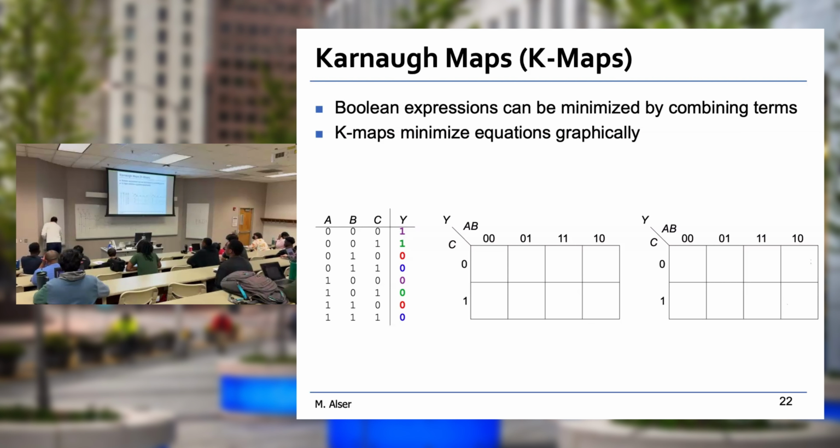Now, we need to build a new table. And this is what we call a Karnaugh map, okay? Now, since we have 3 variables, we always split them into 2 and 1. 2 variables and 1, okay? All the time. Since they are 2 and 1, how large should this table be? For 2 variables, how many permutations can we build? 4, excellent. That is for one side. And since we have another variable, and that variable can be 0 or 1, it should be 2 options for 1 variable, 4 options for 2 variables, and 2 times 4 will give you 8 different permutations, okay?